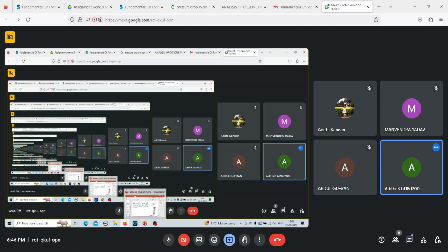Rho, I am substituting it as 1000 kg per meter cube. Omega is 2 pi into n, and n I am substituting as 6000 rpm divided by 60 to convert it into revolutions per second. So this whole square will give me omega square. And r square minus ra square is what we are deriving from here.